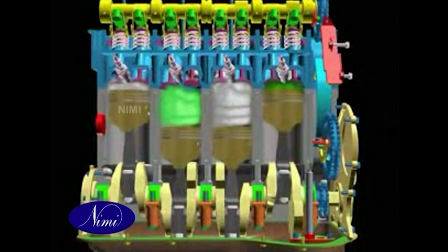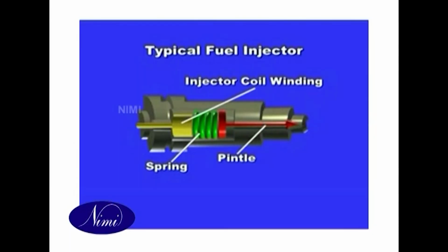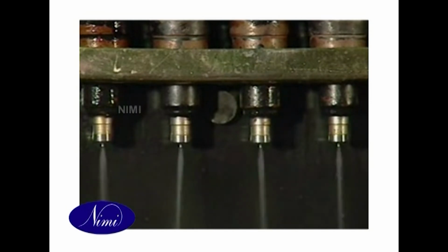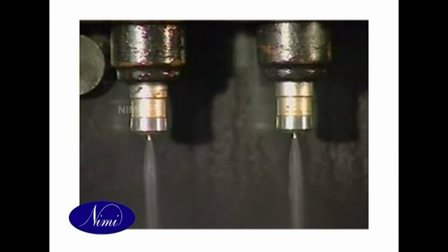The injector receives control inputs from the ECU to open and close the nozzle needle. Modern fast-switching solenoid valve injectors in commercial vehicles can produce as many as 5 injections per working cycle.